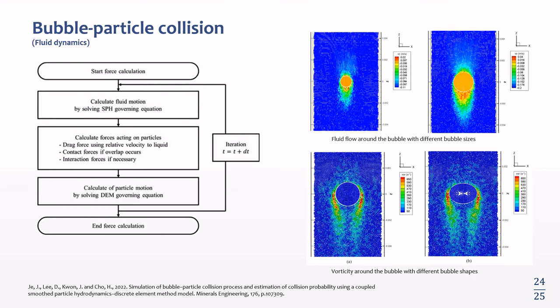So these bubbles, when they are generated, collect the hydrophobic particles and separate them from the hydrophilic particles. So the bubble particle collision, interactions, and the attachment of particles on the surface of bubbles, and the efficiency of this interaction, are so important in froth flotation and its efficiency.